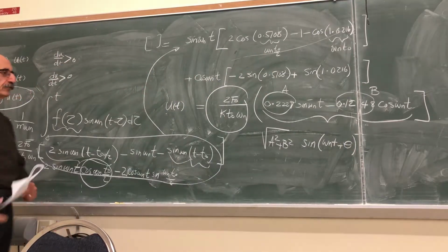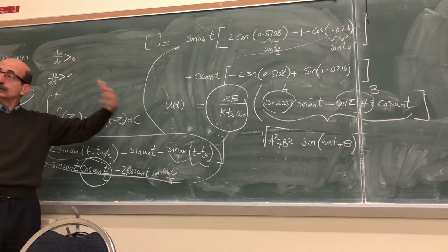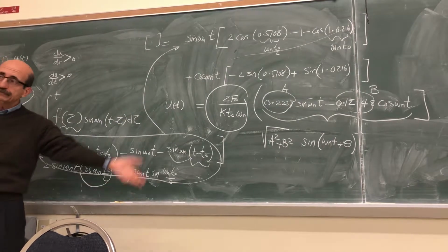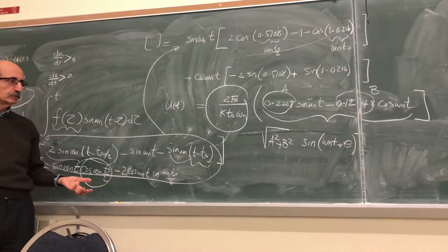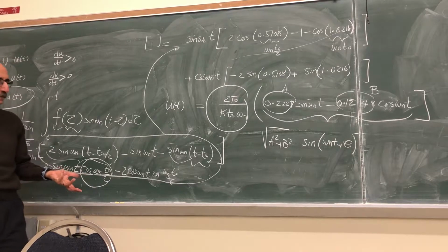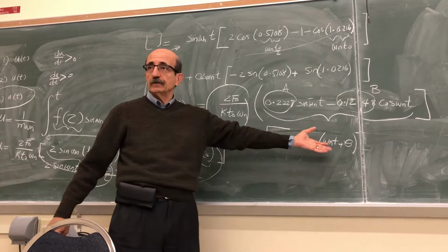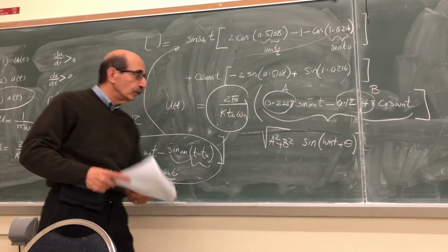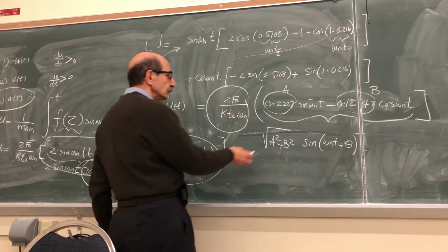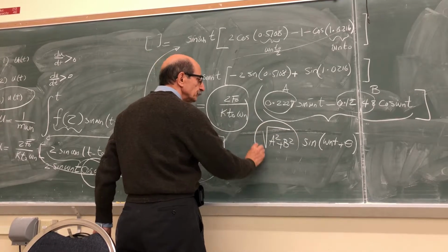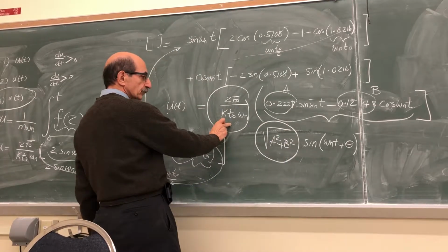So instead of taking the derivative of this, equating that to 0 and finding the maximum displacement that way, we see that the response is basically a harmonic function. So to find its maximum value, that maximum would be just this amplitude times this, right?